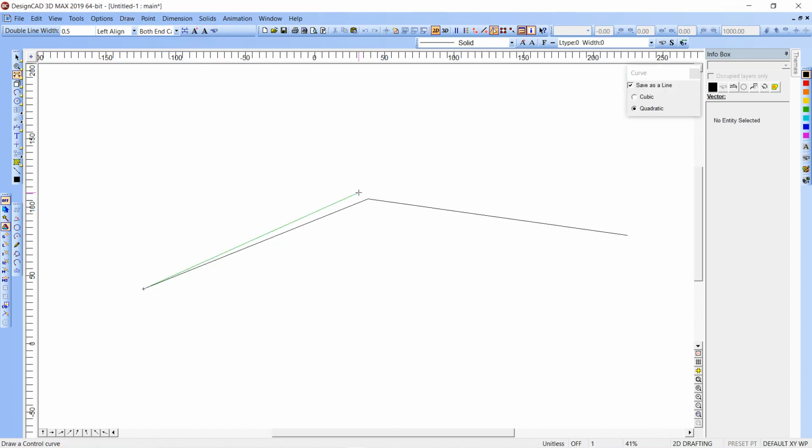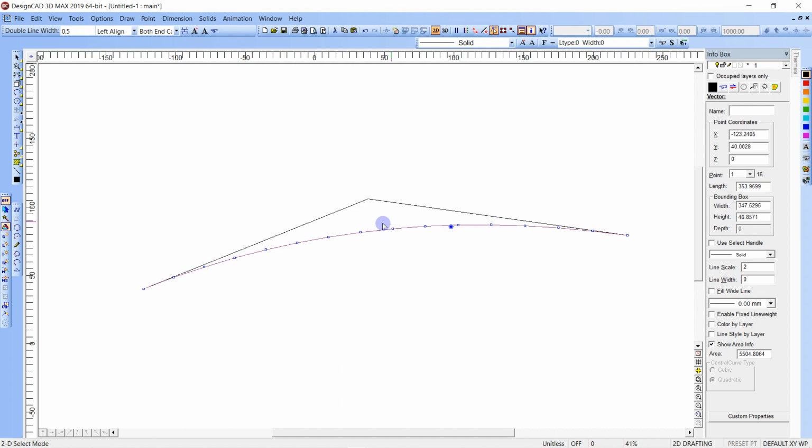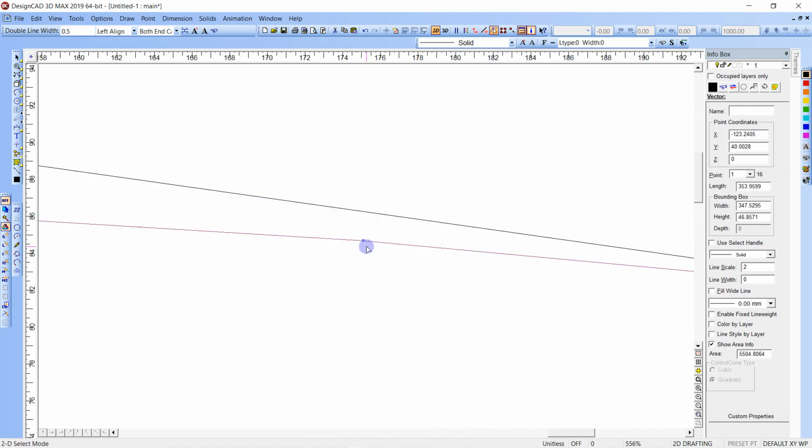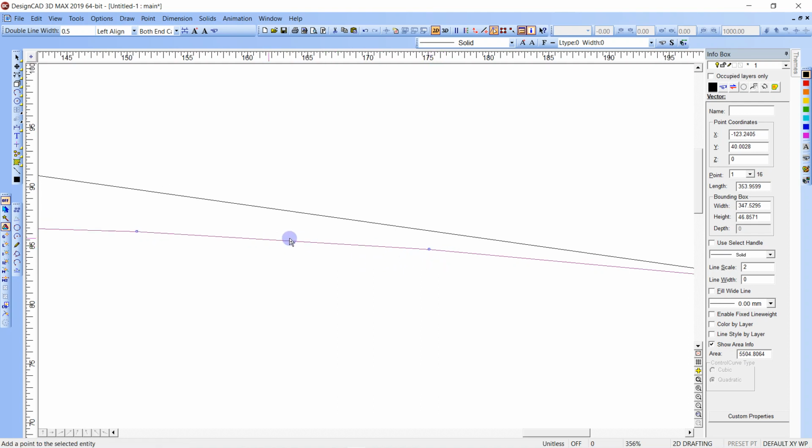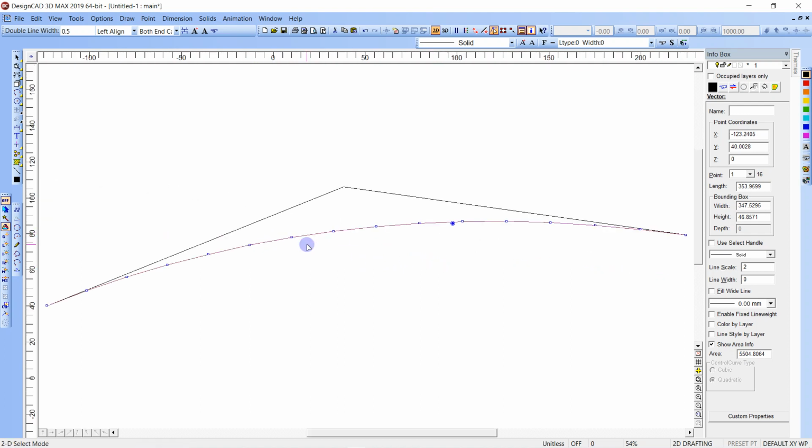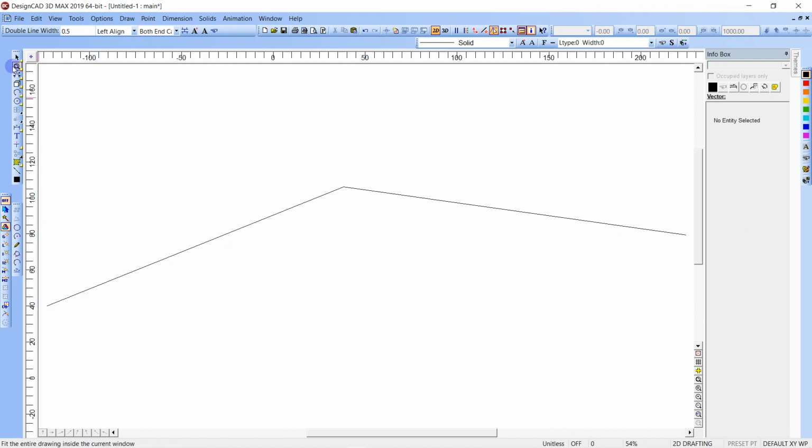You select it there, select the point of tangency, and you select this one, enter, and it gives you a nice vertical curve alignment. Those points are on the vertical curve alignment. The curve that's in between will be missing a little bit, right? There's some work I did on the geometry of a vertical curve alignment that will show you the small difference. So it's very close, but those points are actually on the vertical curve alignment. Those are good parabola points. But like I said, see the sort of straight segments in between there. Those won't match up. Control W, delete, and then let's see what else we got.